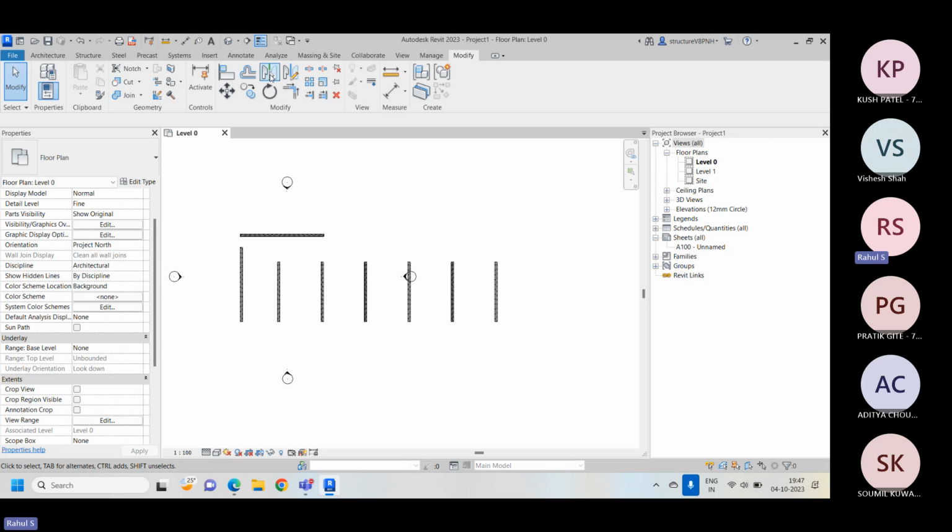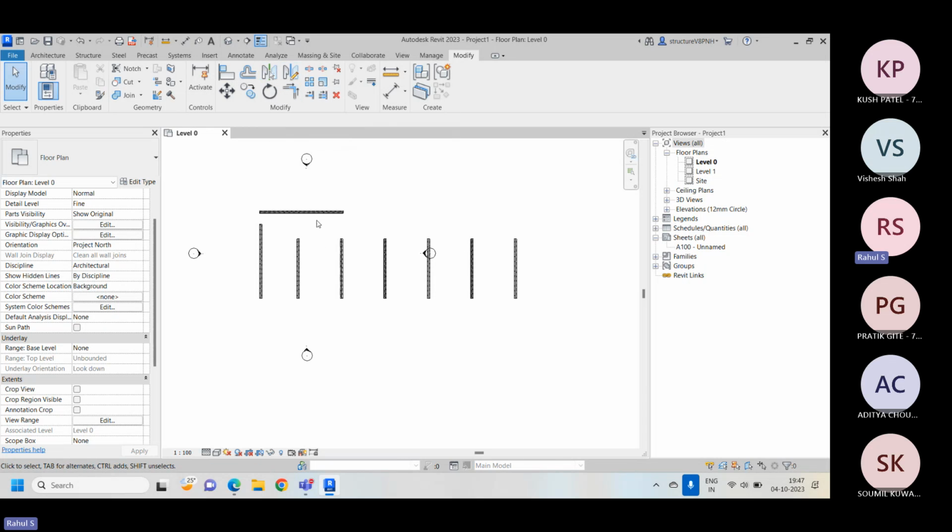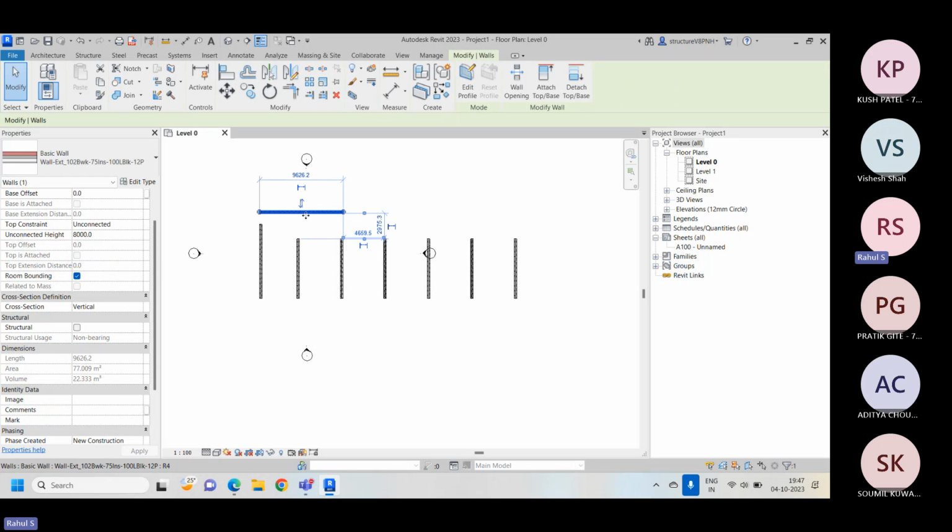Now, mirror pick axis and mirror draw axis. What exactly does mirror mean? Let's say I want to mirror this object, meaning exactly duplicate it at the other surface. So I'll select the object. This is Mirror Pick Axis. Pick means I pick one point, and exactly opposite to that the particular object will get created. And here you have Draw Axis. Let's say I want to create at any distance, so I will just draw one line, and exactly opposite to that, it will create the same object.